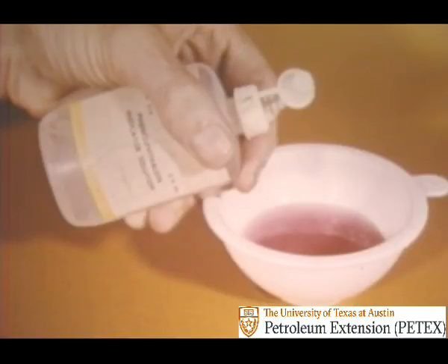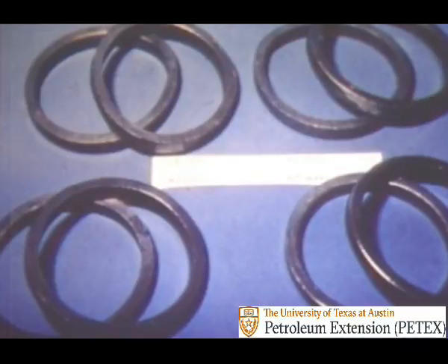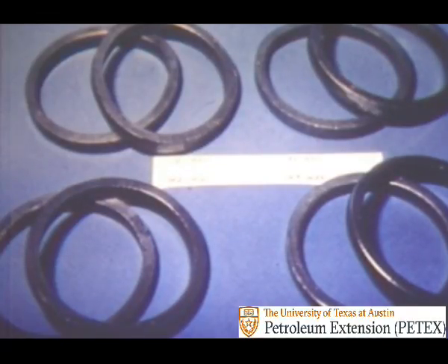Also, the amount of preservative, usually formaldehyde, in the mud can be determined using a test similar to the one for determining the phenolphthalein endpoint. Likewise, the sulfate and sulfide contents can be measured using barium chloride. And since drill pipe corrosion is a problem with some muds, these corrosion rings can be placed in the drill string. After a given amount of time has passed, the rings are removed from the string and the corrosion rate measured.